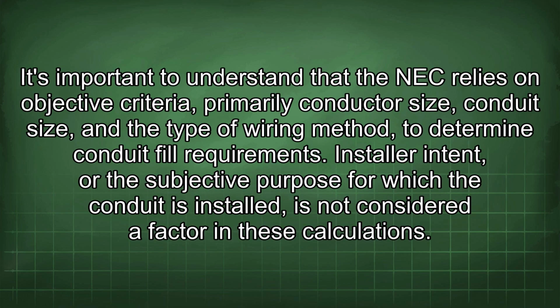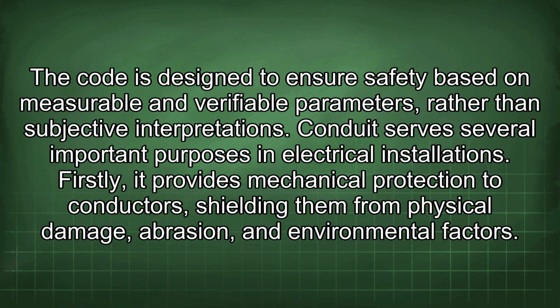It's important to understand that the NEC relies on objective criteria, primarily conductor size, conduit size, and the type of wiring method, to determine conduit fill requirements. Installer intent, or the subjective purpose for which the conduit is installed, is not considered a factor in these calculations. The code is designed to ensure safety based on measurable and verifiable parameters rather than subjective interpretations.